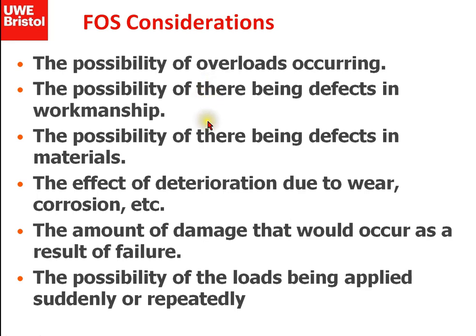Then, in particular for welding and issues like that, you can get defects and local stress rises in the structure, so you have to counterbalance them and over-design a little bit to take into account that the manufacturer, in terms of welding, cutting, and bolting, can cause local stress rises. Then the materials that we get supplied might not be as good as the manufacturers promised, so we'll have to take that into account.